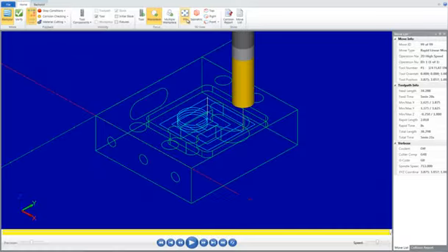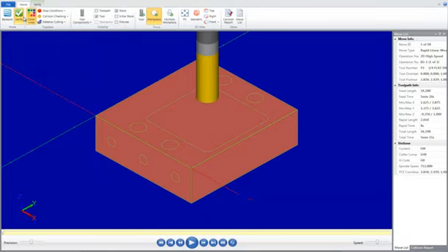We will now simulate the toolpath and verify. From the Mastercam Backplot Home, select the Verify button. Verify mode shows the path the tools take to cut the part with material removal. This display lets you spot errors in the program before you machine the part. As you verify toolpaths, Mastercam displays additional information such as the X, Y, and Z coordinates, the path length, the minimum and maximum coordinates, and the cycle time. It also shows any collisions between the workpiece and the tool.